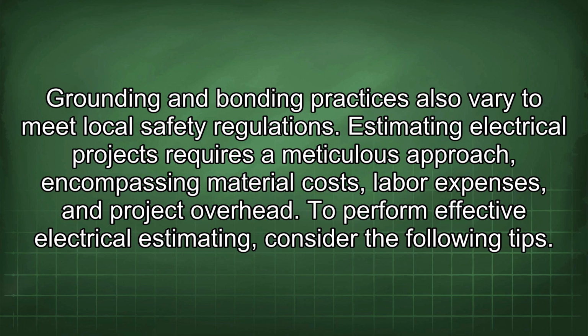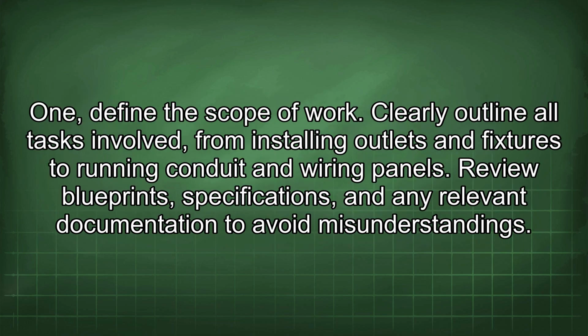Estimating electrical projects requires a meticulous approach, encompassing material costs, labor expenses, and project overhead. To perform effective electrical estimating, consider the following tips. 1. Define the scope of work. Clearly outline all tasks involved, from installing outlets and fixtures to running conduit and wiring panels. Review blueprints, specifications, and any relevant documentation to avoid misunderstandings.